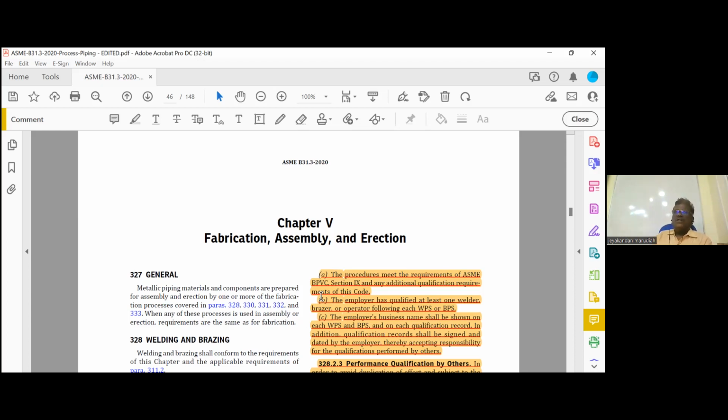Okay. Now, that weld is called a longitudinal weld. The efficiency you are taking is for a longitudinal weld. But in fabrication, when you receive the pipe with the fittings and we are making piping spools, fabrication or erection, we are not making a longitudinal weld. What welding are we making actually? Circumferential. There is one more technical name for that weld, called girth weld. What you are making at the site is called a girth weld or circumferential weld, pipe to pipe weld.